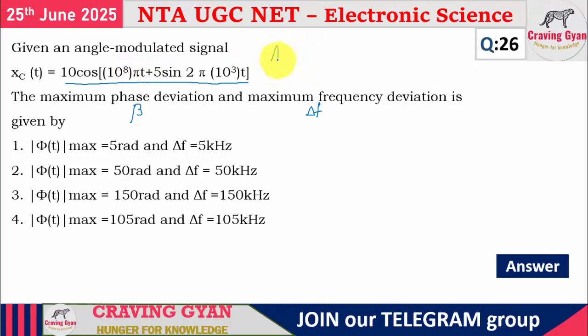You have to compare it with the standard equation, that is Ac into cos of (2 pi fc t plus beta into sine of 2 pi fm t), nothing but omega c t plus beta into sine of 2 pi fm t. This equation we have to compare. Now tell me what is the value of Ac.